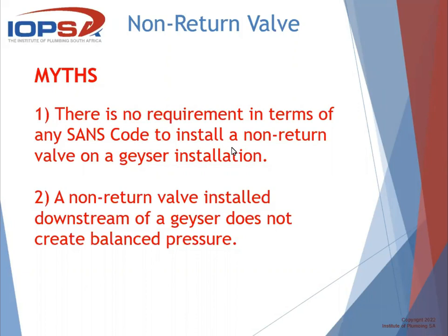Yeah. You also mentioned something about a ring feed with a pump system. Yes. Yeah, look, just staying on non-returns, I think it might be worthwhile mentioning, because we're talking about non-return valves, that we must always bear in mind that a non-return valve, a single check valve, is not what the standards define as a backflow prevention device.